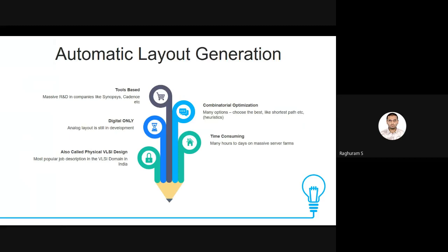But today, 70% of the delays are due to the interconnections, not because of the actual gates, because the transistor has become so small that the delay has become very less. But because the number of transistors is so high, there are just so many interconnections between these blocks, inside these blocks, that the delay of the interconnection is much higher than the actual delay of the logic. It's a very strange thing, but that's how it has become today.